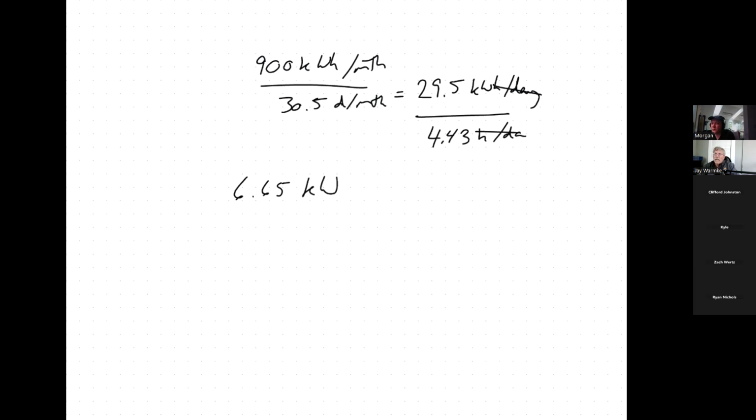But we just figured out it's not 100% efficient. We figured out it's only 95% efficient, right? Because we did our D rate. So 6.65 divided by 0.95 is going to get us exactly like 7 kW. So that's how you size that array. That we need for this house a 7 kW system. So that's how we get to sizing our array. It's a 3-step process.